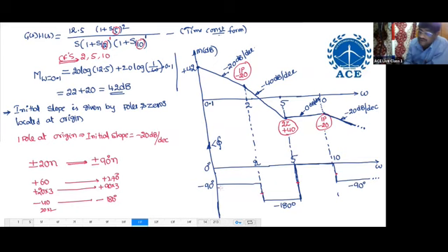Start below the 90 because the plot should pass through this point. So minus 90, a little bit close to the asymptote, not very close. Again, past the midpoint, a little bit close to the asymptote, and then draw it like this. This is called the phase plot.